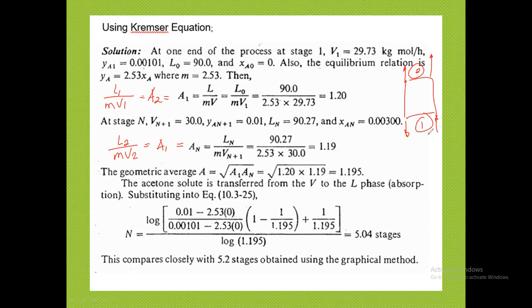So it was emphasized last meeting that you have the gas introduced at the bottom and the liquid introduced at the top part of the column. Okay? So this is on that orientation. With all 4 phases known already, all L's and all V's known, you can determine the 2 absorption factors. One for the top of the column, this is the concentrated N, and the other at the bottom of the column, which is the dilute N. Oh, sorry, this is the concentrated N, by the way, and this is the dilute N.